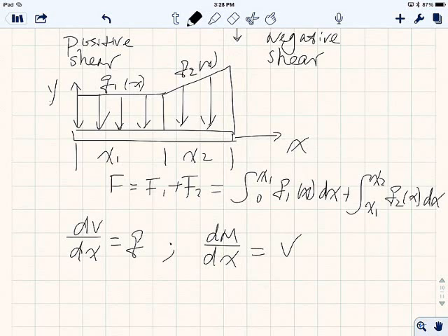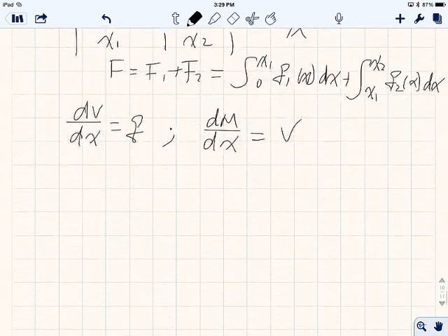You break those functions into very small pieces and add them together. That tells you if I give you a regular distributed load, either horizontal or linearly increasing, you can calculate the amount of F1 by calculating the area underneath this curve. Make sense? I'll go into more detail when we see an example.